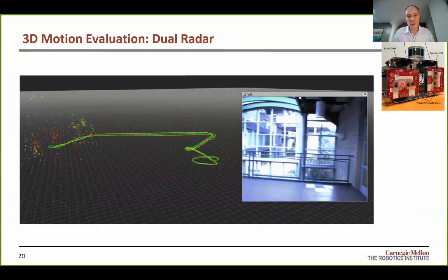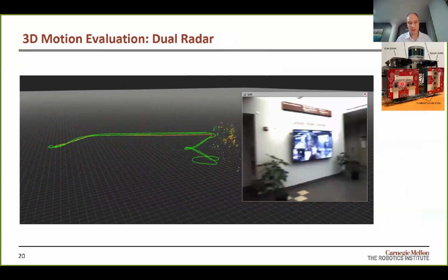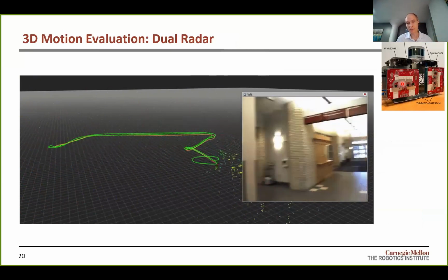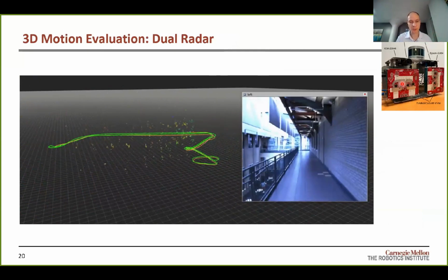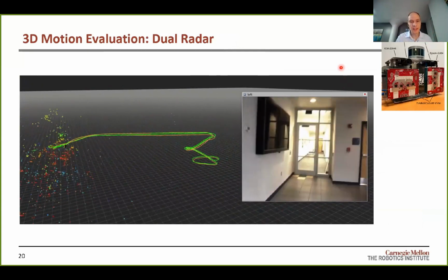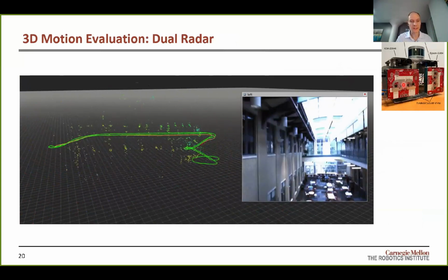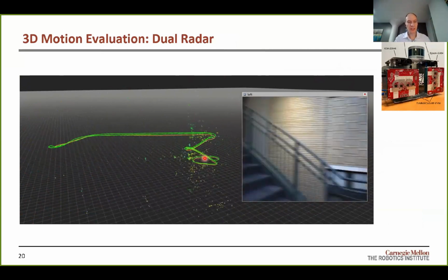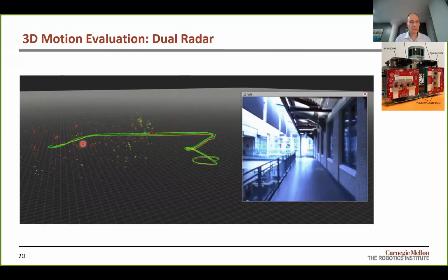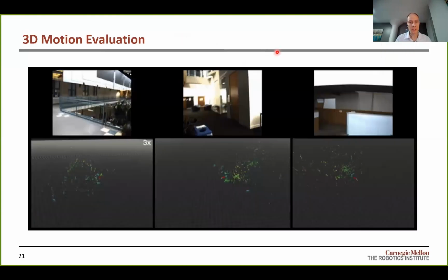They are typically for outdoor environments, long range, and not very good resolution and velocity, but you can reprogram them for shorter range and get good velocity resolution, Doppler velocity. And then also use 2 different frequency ranges for the 2 radars. And so with this, we can here go, including stairs, go through an environment back and forth, and we have almost no drift over that course.